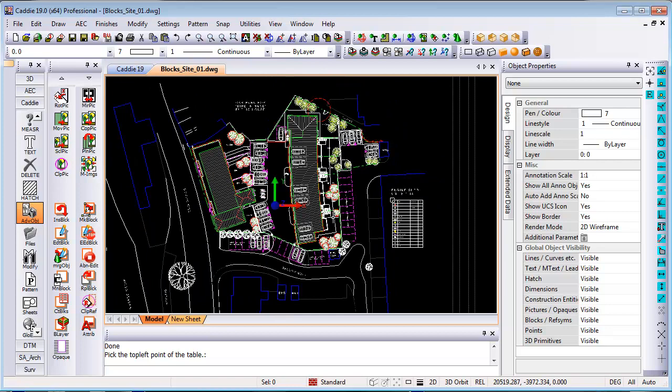So to recap, in what instances will blocks be used and where will it be useful? It is especially useful if you've got objects that are duplicated within drawings. So before you copy something which will be duplicated in a drawing, you first make it a block, and then the block reference you can copy any number of times that you want to. First of all, it reduces your drawing size, it speeds up the performance of your drawing and the memory usage. And secondly, it gives you the ability to globally edit them.